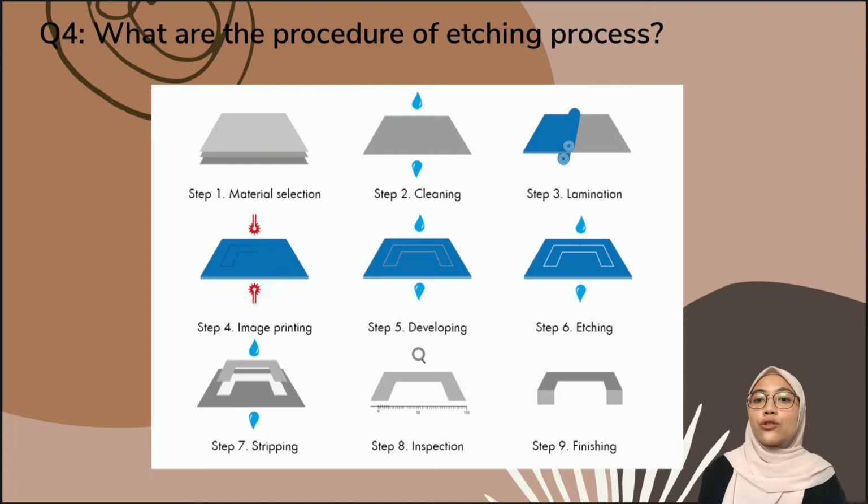Chemical etching can also produce very accurate engraved features at the same time the material is being profiled, such as fluidic channels, logos, or part numbers. These features come at no additional cost. The minimum standard etch opening achievable is 0.1 mm. With development, even finer features can be achieved.